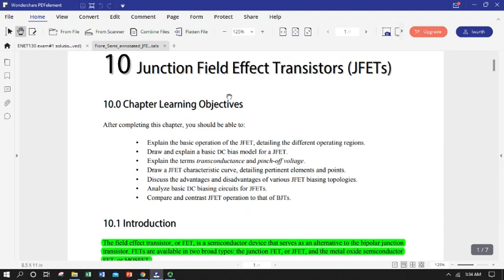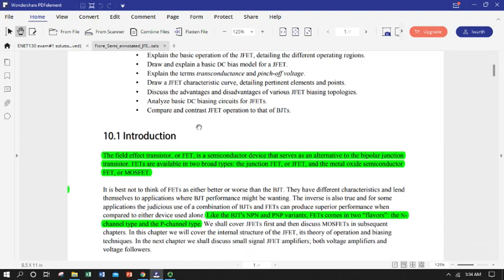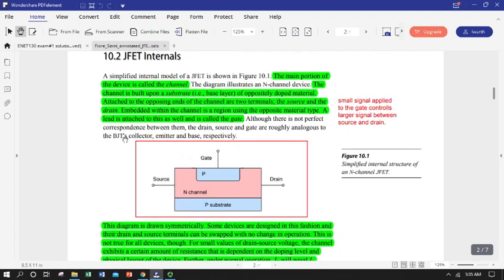So, general idea of a transistor. Like in the case of the BJTs, field effect transistors are going to allow us to use a small signal to control a larger signal. That's the whole idea of transistors in semiconductor or vacuum tube devices. Small signal controls larger signal. But rather than doing it by having a small current control a larger current, or a current control current source, which is what bipolar junction transistors do, a field effect is going to use a small voltage signal to control a much larger current signal. So it's a voltage control current device or current source.